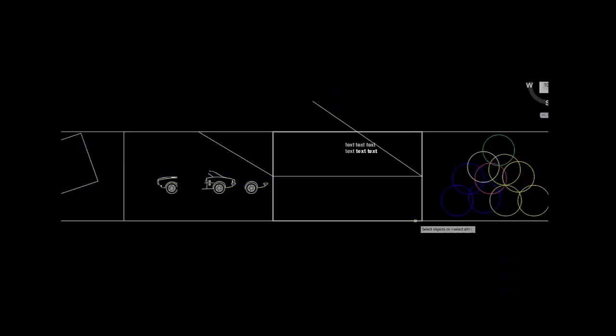If I start the extend command, selecting all objects, and extend this line out, I can hold down the Shift key and it'll act as the trim command within the same object.